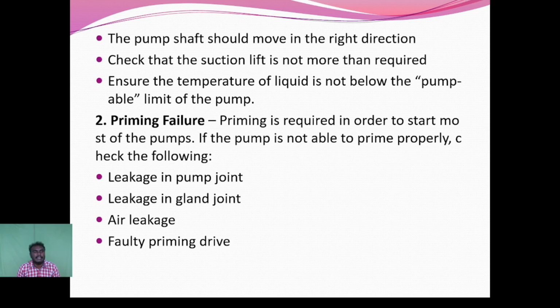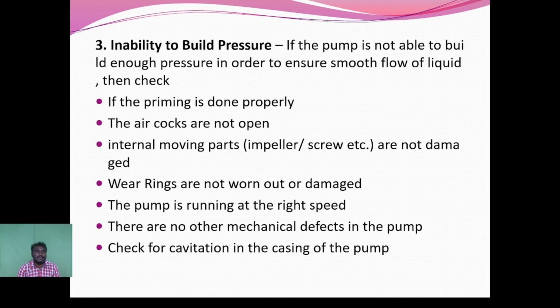The second thing is priming failure. Priming is required in order to start most pumps. If the pump is not able to prime properly, check the following: leakage in pump joints, leakage in gland joints, air leakage, faulty priming, and drive.